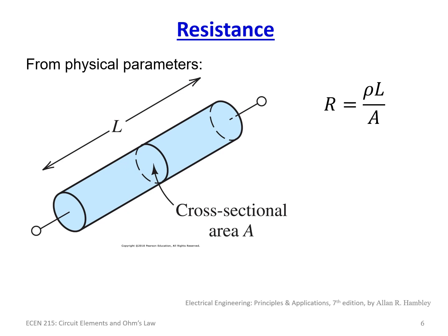So what is resistance? Resistance is, again, dealing with the cross-sectional areas. So resistance is a constant times the length of the conductor itself, length of wire, length of a trace on a circuit board, so on and so forth, a length of any type of conductor, divided by the cross-sectional area of that conductor. So if you have a wire and you have a larger cross-sectional area where A increases, that is going to decrease proportionally the resistance.